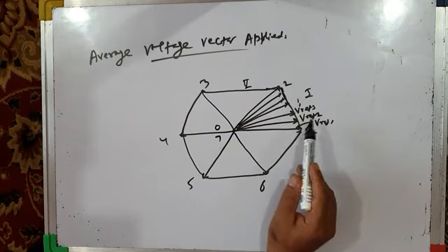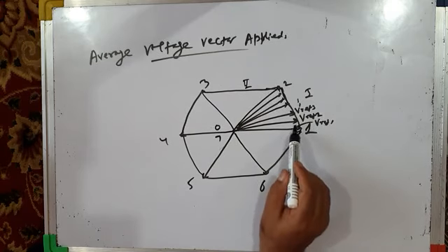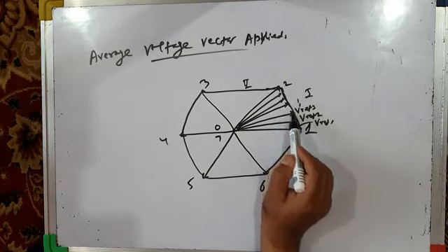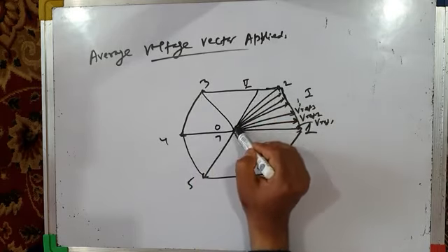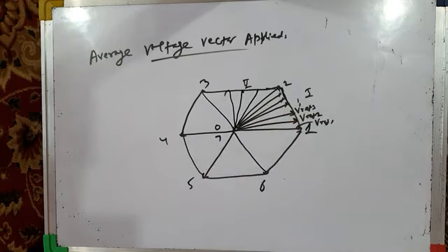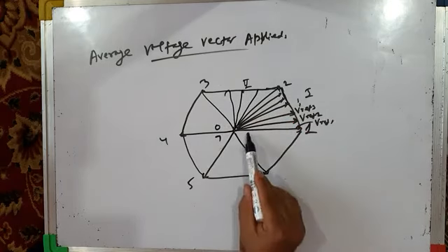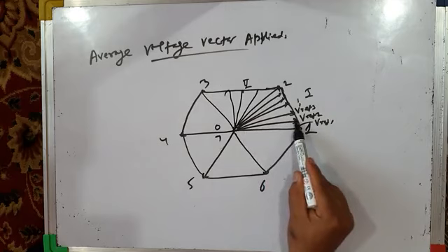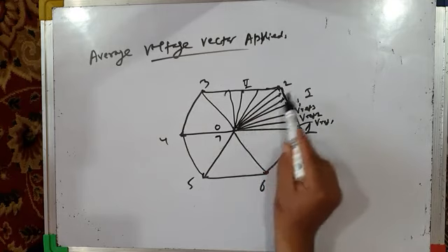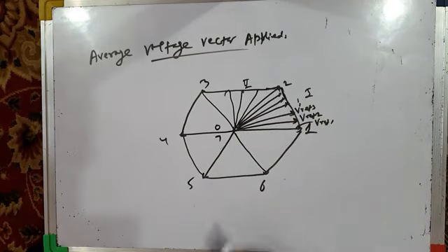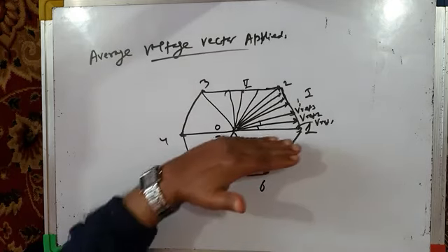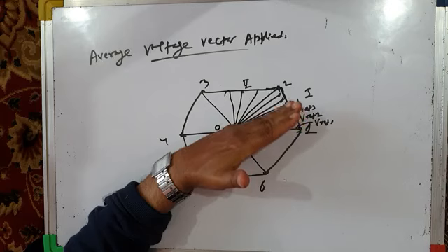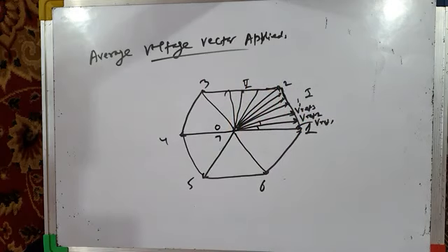So your reference voltage vector moves along the boundary of the hexagon or triangles. In sector 1, sector 2, like this, it will move along this. Here it will have some magnitude, here a different magnitude, and so on. But as far as the angle is concerned, it varies linearly, at the same speed.